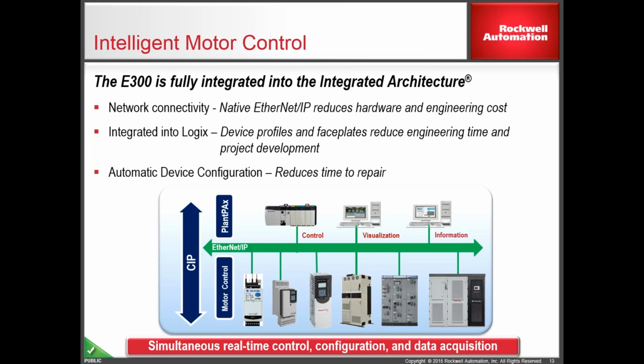With that add-on profile, it'll allow us to configure our E300, and it also brings in a lot of those controller tags that we can use to create our program. It's really nice because they have the proper naming convention on them, and they're very descriptive, so it makes it really easy to figure out what tags you want to use for your Logix program.